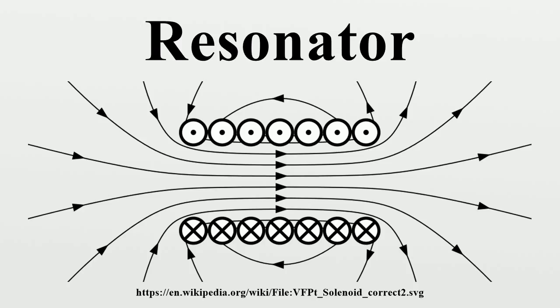A distributed parameter resonator has capacitance, inductance, and resistance that cannot be isolated into separate lumped capacitors, inductors, or resistors. An example of this, much used in filtering, is the helical resonator. A single-layer coil that is used as a secondary or tertiary winding in a Tesla coil or magnifying transmitter is also a distributed resonator.